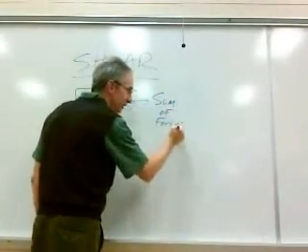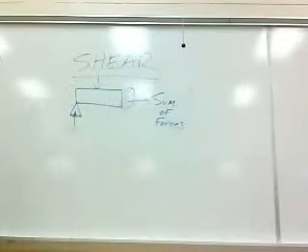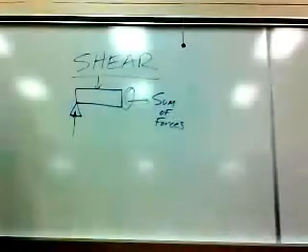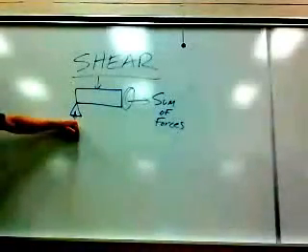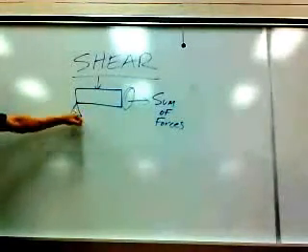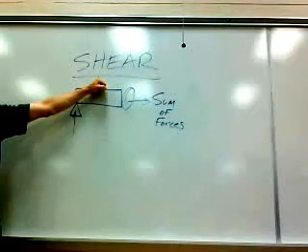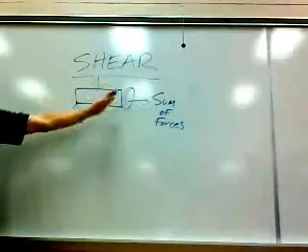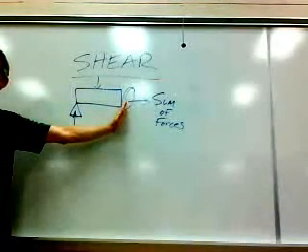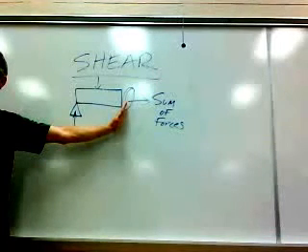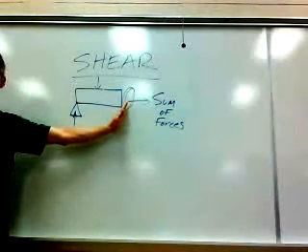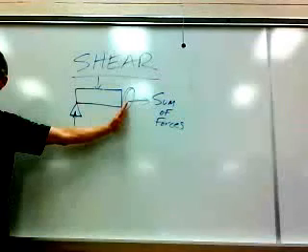That was the definition of shear at a particular location. So if this was 1,000 pounds up, and the only other force you had on there was 300 pounds down, at this section there'd be a shear force of 700 pounds up. Okay? That's what we learned in strength of materials.